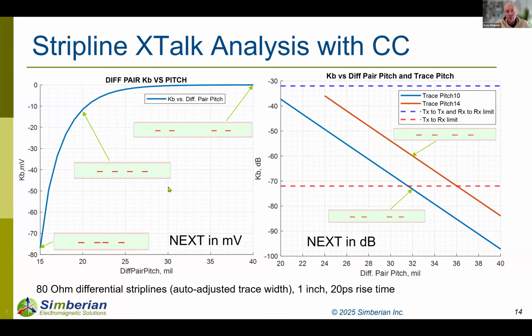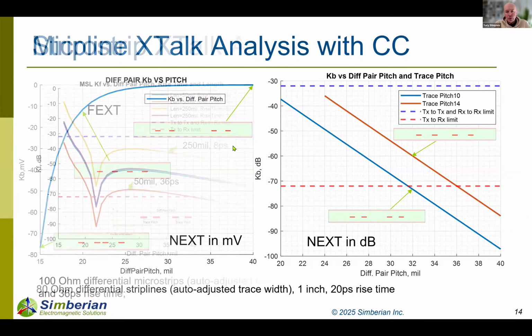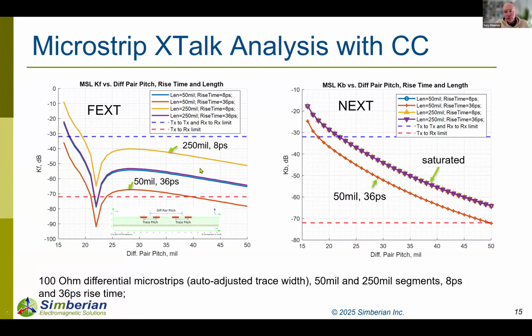And this is just linear scale. On linear scale, it's not so obvious how it behaves. This is far-end crosstalk or forward coupling coefficient. You can see the behavior is a little bit more complex with microstrip line. So you can see even minima defined by the solder mask. You can adjust solder mask parameters to have very low far-end crosstalk, but it's purely theoretical. So in reality, manufacturing with such precision is practically impossible because solder mask doesn't have any kind of precision when it is applied.